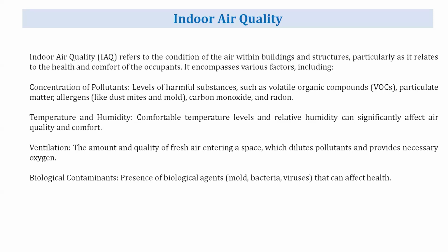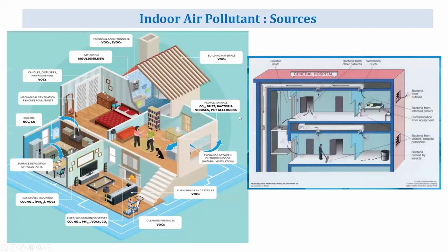Biological contamination also comes under the concentration of pollutant. The important thing is mold, and this is directly related to so many things because once mold gets suspended into your indoor air, it is recirculating and you're breathing it, and it gives rise to fungus generation and all those things. It starts off with headaches. Straight away, if you are not comfortable in the building and you have a headache, this can be a possible cause, which you can easily identify with a visual inspection.